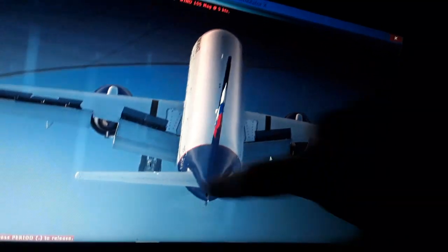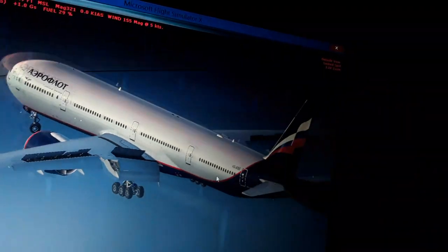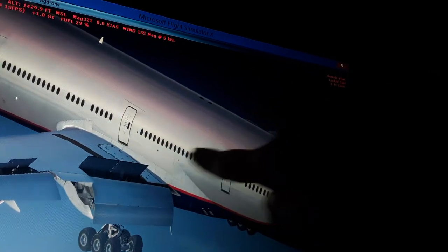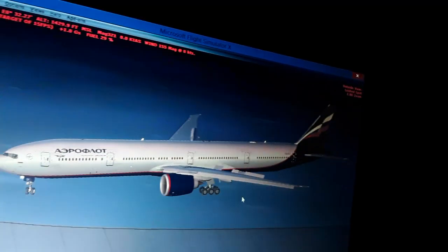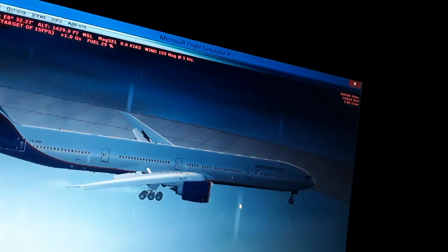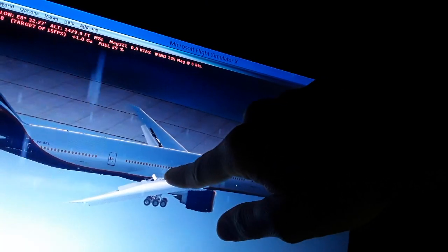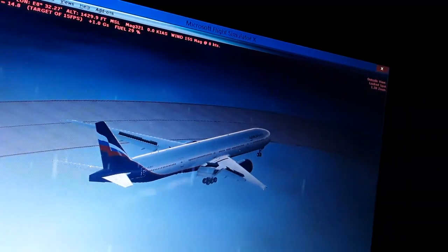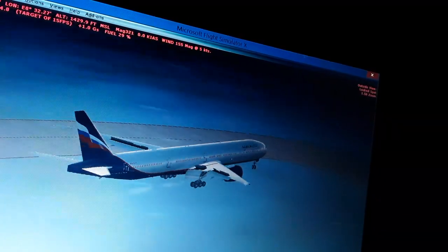So the horizontal stabilizer and the vertical stabilizer are positioned with angles transversing this axis here, and also the position of the center of gravity and the mean aerodynamic chord of the aircraft. It's about 85% of this position. So the center of gravity should be here, where the mean aerodynamic chord is 35%. It should be forward or aft of this position a little bit, not too much, or it will make the aircraft lose its stability, or become more difficult to control.